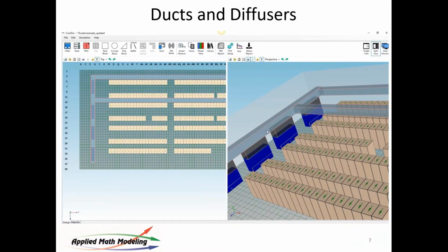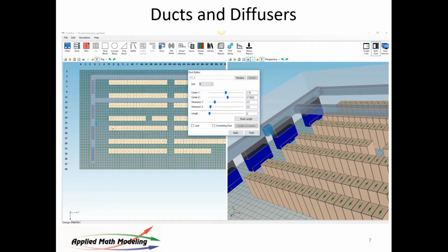So that's one method. Here I can see this one, so I just right mouse click it and say Add Duct. You can always point and click with your right mouse, but you can't always rotate the geometry so it's visible to you with the mouse. So you can do it from Duct Designer using the XYZ coordinates and so forth, or you can just point and right mouse click it and say Add Subduct.